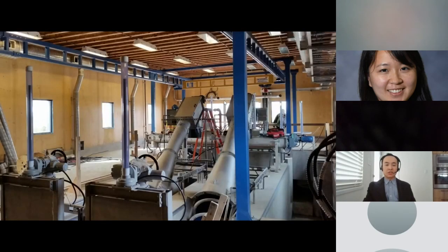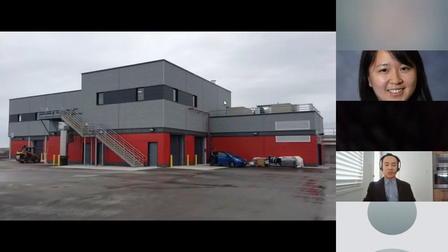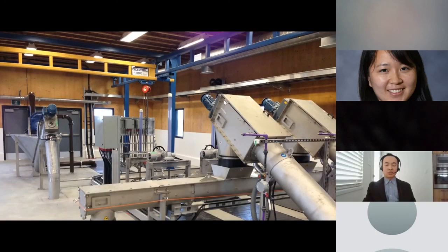This is the inside of the process building. This is the outside with all the finished cladding and stuff like that. And then going back inside the process building again, in order to protect the wall panels from vapors and splashes of the processes, we not only had to apply a marine type of varnish or sealer on the CLT panels, but to provide additional impact and abrasion resistance, we also had to apply a fiber reinforced type of liner product near the bottom 3 or 4 feet or so, as shown in white there on that wall panel.